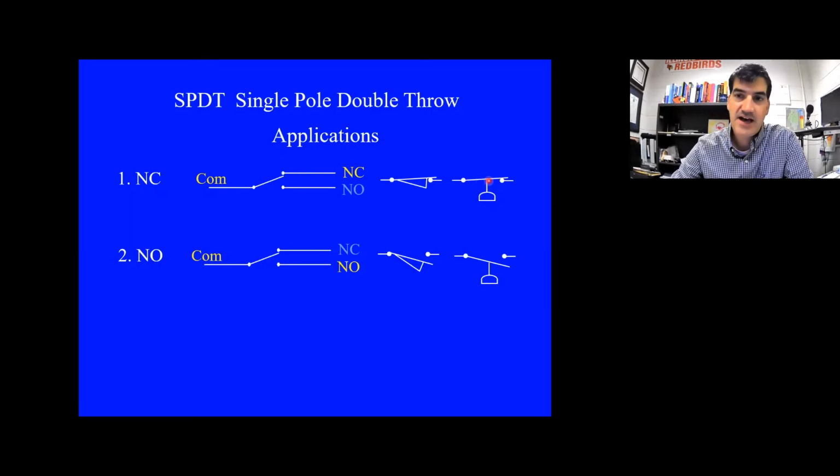All right. Conversely, you can use a normally open connection, and you can have a normally open limit switch. So this does not have a connection here, no continuity through here for current to flow, until something presses on it or activates it and moves this switch right here. All right, so there's a normally open limit switch. Here's a normally open float switch.